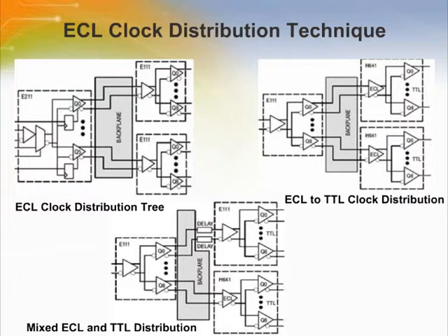An emitter-coupled logic clock driver will be significantly faster than a TTL or CMOS equivalent function. Therefore, to deskew the emitter-coupled logic and TTL signals, a delay needs to be added to the input of the emitter-coupled logic device. The value of the delay element would be a best guess estimate of the differences in the two propagation delays.